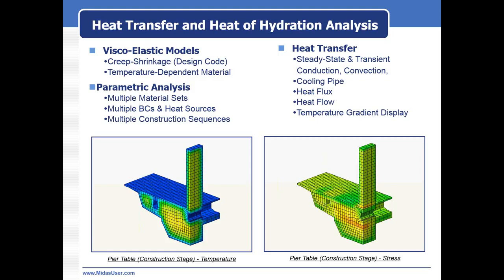But the thing is, in Civil, we can model the solid elements, but reinforcement cannot be defined in solid elements. And as bridge engineers, you know that sometimes it's very much necessary for mass concreting structures to define the reinforcement and then perform heat of hydration analysis, just like a pier cap.